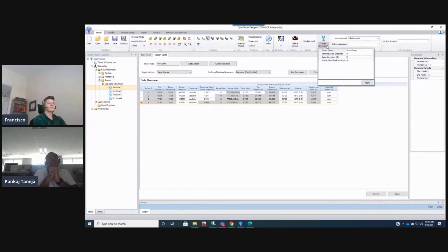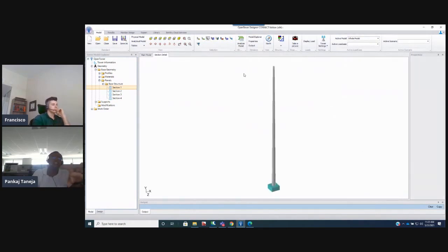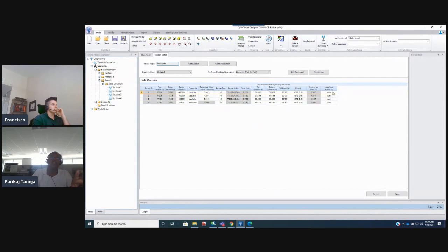Think about it this way. If users have the information on bend radius, they don't have to stick to four times the thickness. They can define it instead of auto. Let's say, based on TIA-222-H, we put 1.5. Now if I save it, it will still say auto. It will not change. You can enter the information here too, it doesn't have to be auto only. Auto means it will automatically assume 1.5 times the thickness, or whatever inside bend radius factor you define. Gotcha, that makes sense. That helps the users a lot.